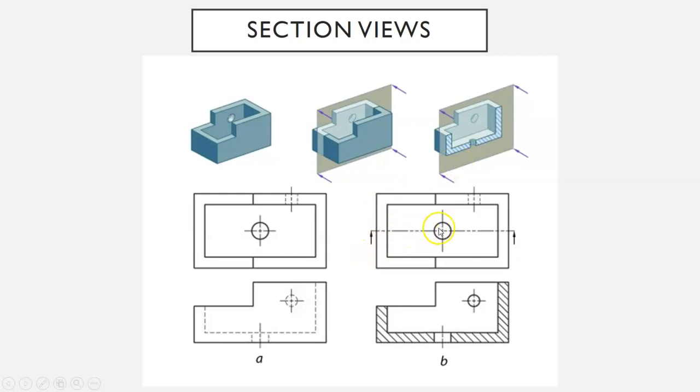In the view that we sliced, we're going to draw these little section lines right here to show that, hey, this is where we're chopping and this is the direction that we're looking. And in the view that was actually sliced, we need to color it to show that those parts were actually affected by the cut itself.